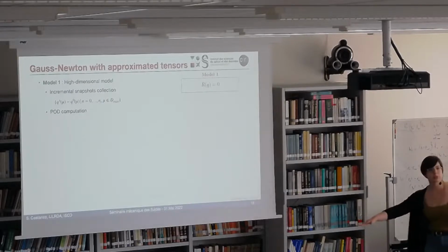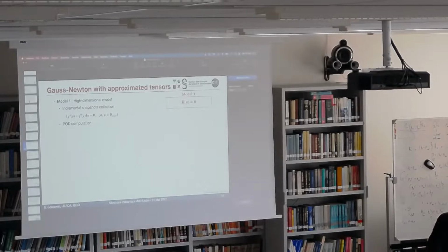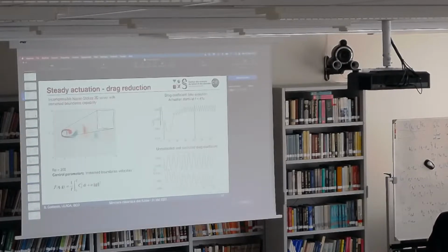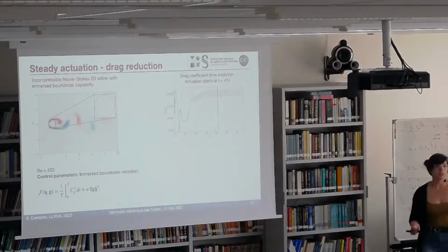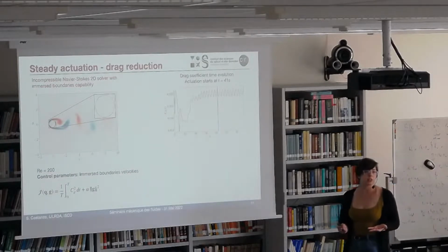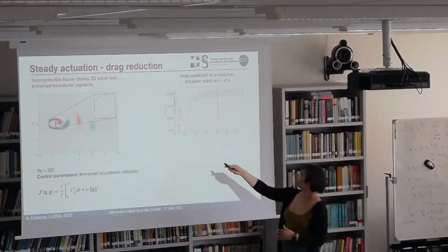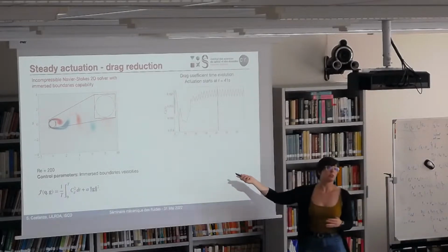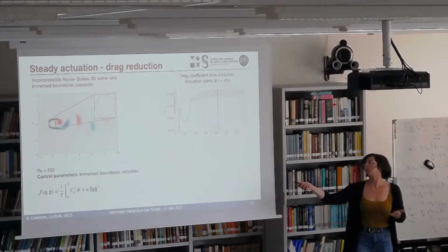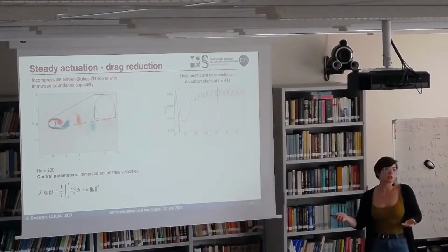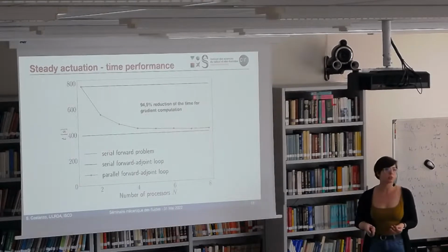Yeah, it probably keeps going there. But actually the thing with this case is that it's not how you physically would do that, because we are using an unsteady optimization, right? Versus a steady actuation. What you do usually is use an unsteady optimization that, according to the phase of the oscillation, governs the blowing action at the top or at the bottom of the body. So this is just to show, I mean, we're not very interested in the reduction of the drag, we're interested in the performance of the algorithms, just toy problems to validate the method.